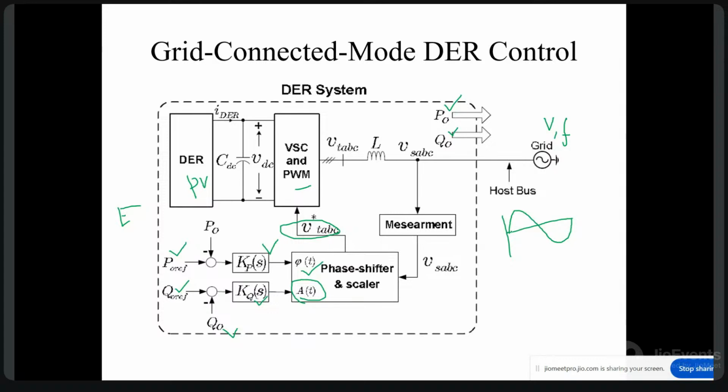We have studied, all of us, whether you are from power systems or power electronics or any other branch, the sinusoidal PWM. So we are going to generate the sinusoidal modulating signal, and we are going to have the carrier wave. Wherever we have the crossovers, at those crossover points we generate the switching pulses, and our power electronic converter will be fired as per the generated switching pulses. All right, is that clear, or any questions? Yes, sir.